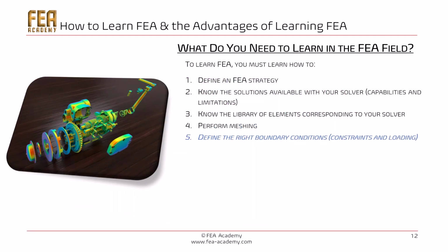Also, you will need to learn how to define the right boundary conditions. By that, I mean the constraints and loading. It is one of the most complex problems you will have to solve as an FEA analyst. You have to know that the boundary conditions influence a lot the results.